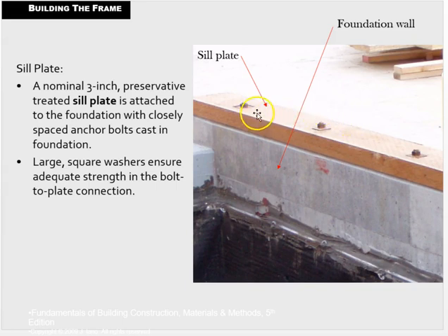Either way, this is an extra big 3-inch pressure treated sill plate. So this is not your ordinary 2x sill plate, and it also has the spacing of the anchor bolts very close. So this is a heavier duty application.